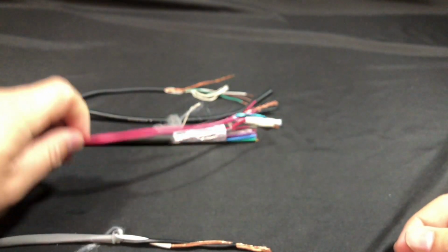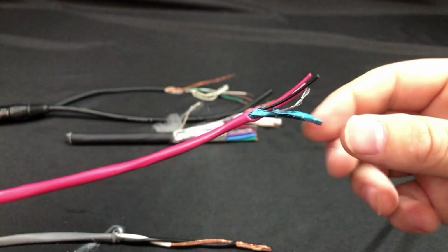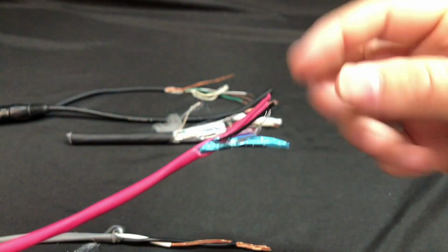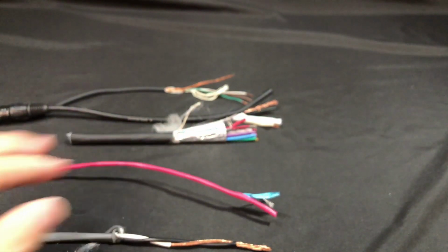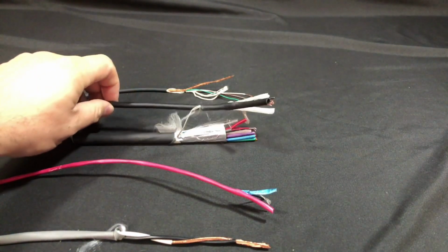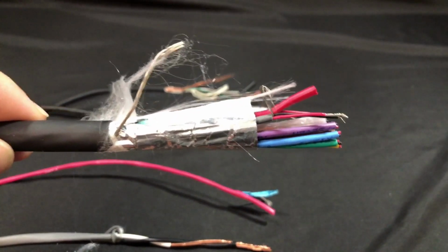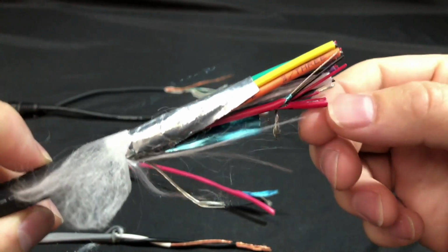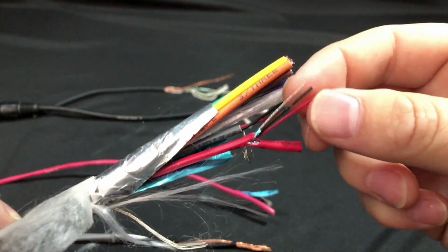The next is another speaker cable with a lower gauge, so just a smaller conductor. I guess technically it's a higher gauge, and all it has is a foil shield around both of the conductors together. So the conductors themselves aren't isolated from each other, but that's going to have good radio frequency interference rejection, which for a speaker cable at high voltages is good because otherwise it's going to act more like an antenna. And the next here is the braid. I'll go with this one here. This one also has foil around the outside of the entire cable, but then it also has foil inside each conductive sleeve, but not in between each smaller conductor.